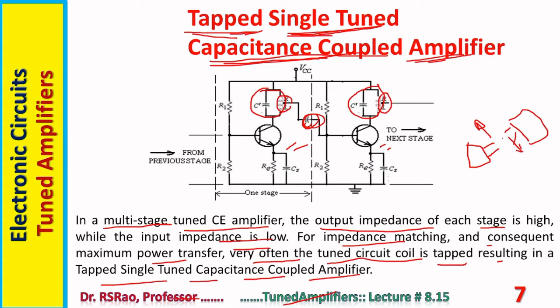If we provide a connection without adjusting their impedance levels to the same level, a mismatch comes into being, and the output of a stage cannot go completely into the input of the next stage. Reflections happen. To avoid this situation, and to see that the output of one stage goes completely into the input of the next stage, a certain kind of matching has to be performed. In the present case, matching is done through tapping. So the purpose of tapping is to provide an impedance match between the output of one stage and the input of the next stage.